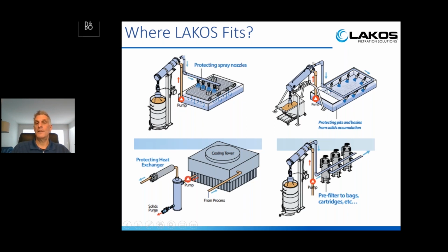Or when you're cleaning basins or tanks or sumps, we use a series of what we call hydro boosters or eductors, which are basically little venturi jets that are placed inside the tank to make sure that we are getting the solids to the pump that's going to feed the filter, in this case, our separator.